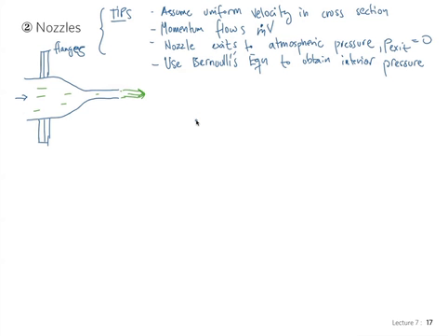Well, let's look at that. Basically, if I draw a control volume around this thing, whatever is inside that control volume is like a black box. I don't see what's happening, right? And as long as I know the momentum that comes in and the momentum that goes out, I'm going to get the same result, regardless of what's happening inside.